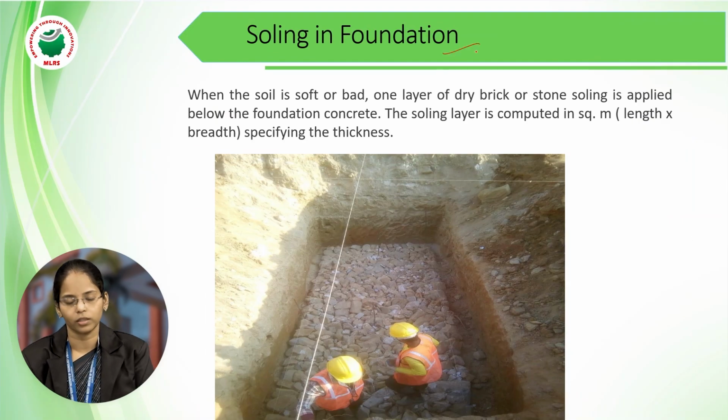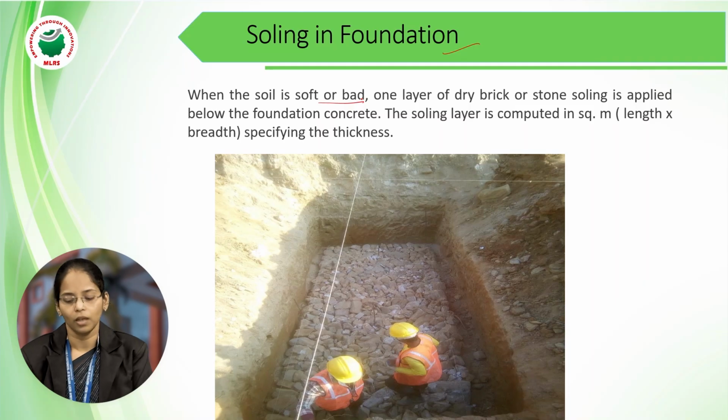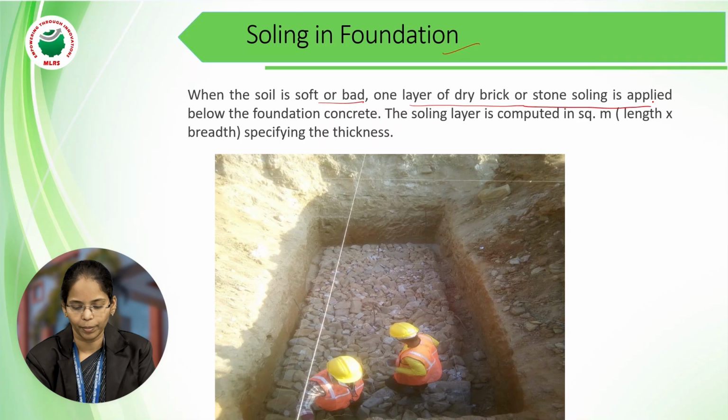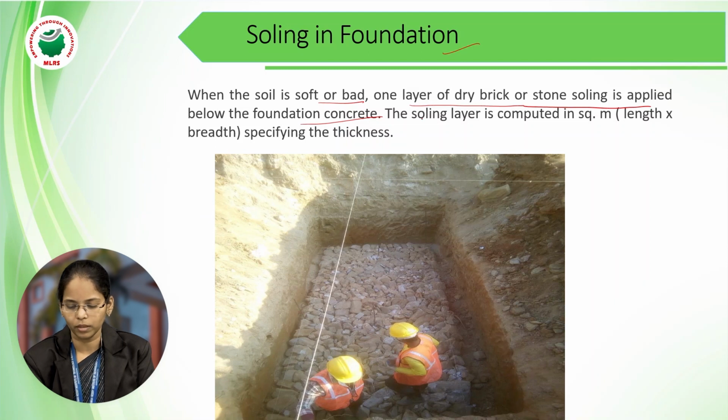Next, soling in foundation. Soling is nothing but, after excavating and preparing a trench, if the soil is soft or bad or loose, then what we do is apply one layer of dry brick or stone soling below the foundation concrete. So before laying the foundation, we need to prepare this one layer of dry brick, so that it gives some strength to the soil.